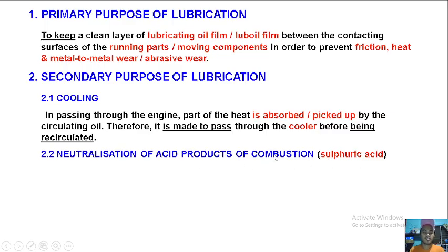Since our piston has cylinder lubrication, the other purpose of cylinder lubrication is to neutralize the acid products of combustion, since sulfuric acid and vanadium can cause damage to the piston head and the liner. Next is cleaning.